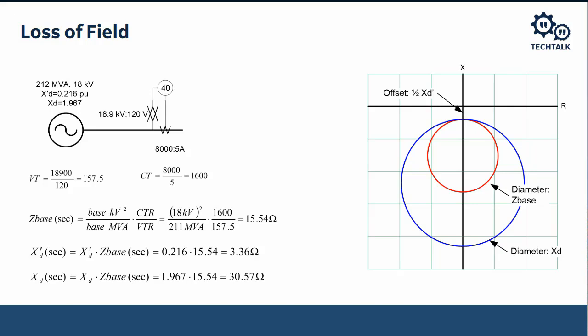When we lose the exciter, our apparent impedance point ought to move down into one of these impedance characteristics that I show on the screen. The apparent impedance point would move along the reactive axis, so it would be below the origin, and it would also move in because we're not able to provide as much real power, as seen by the ring down in current. And so we would move into one of these regions.